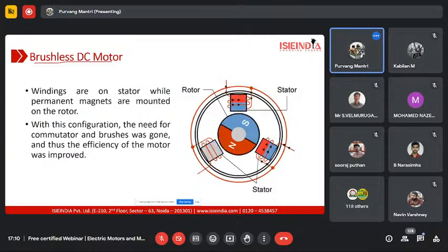This is done in such a way that one stator winding would be attracting the magnet pole of the rotor, while the other stator winding would try to repel it. Because of this repelling and attraction, the permanent magnets of the rotor would keep rotating, and it will generate a high amount of torque. There will be pretty minimal torque ripple compared to a brushed DC motor.